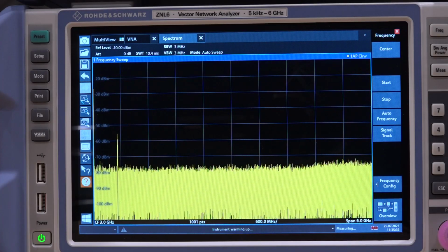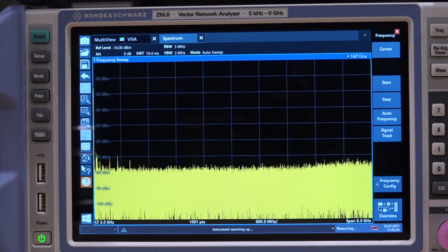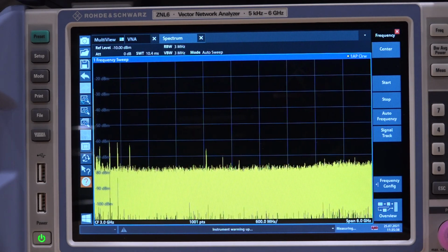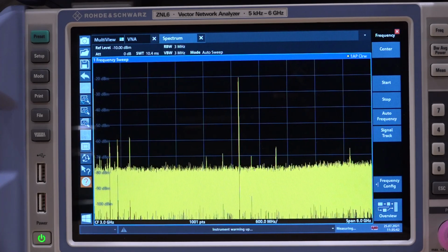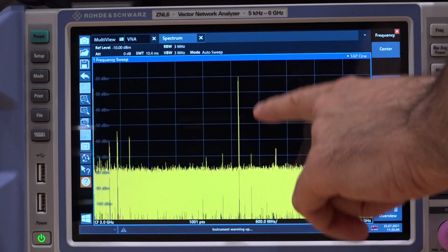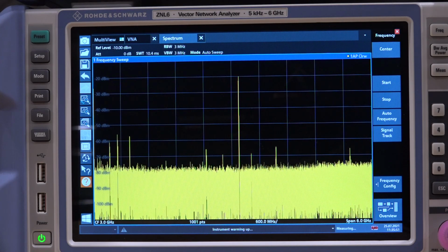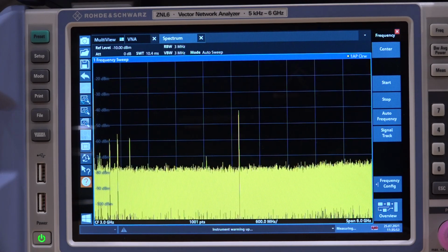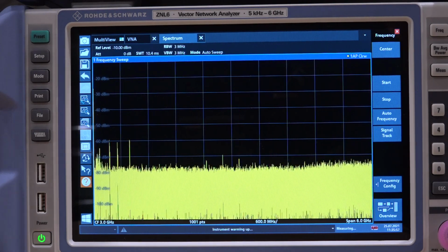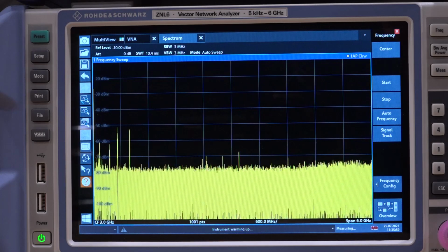Okay, let's go ahead and do our probing measurement one more time. Let's go back to the output of the VCO, and let's see what we see here. If I can probe it properly. Here's the output. Look at that. This is the 3 GHz signal. Look how steady that is. That already tells me that the PLL is locked. That's why the signal is not moving around. The synthesizer itself is at a fixed frequency in this situation. There's no sweeping. So look at that. Yeah, it is locked.